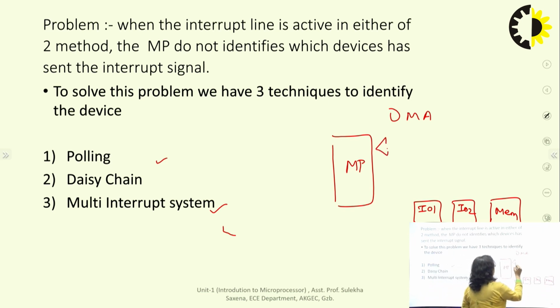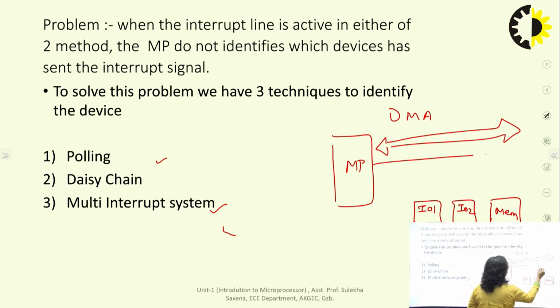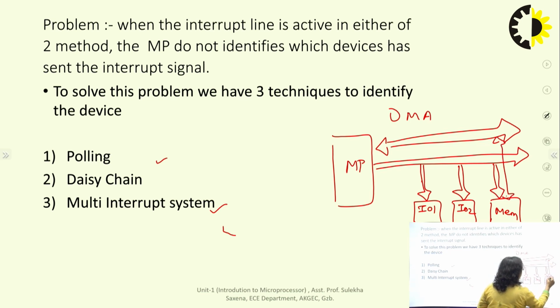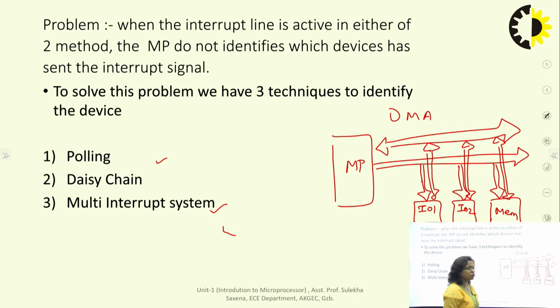Once an IO device has to transfer bulk data to memory or vice versa, it requests the microprocessor through the hold signal. Once the microprocessor receives the hold signal from the IO device, it completes the current execution, saves the status and releases itself, or tri-states itself, from the system buses, that is, remains in hold state, and releases the acknowledgement to the IO device.